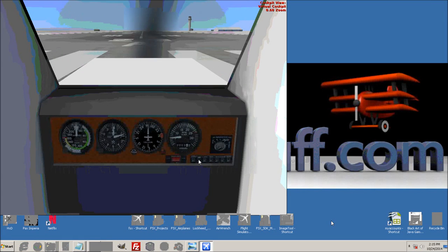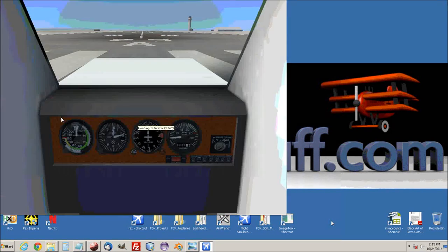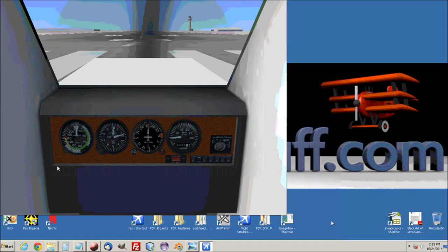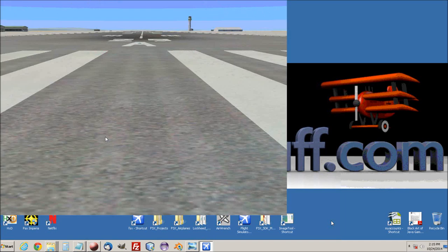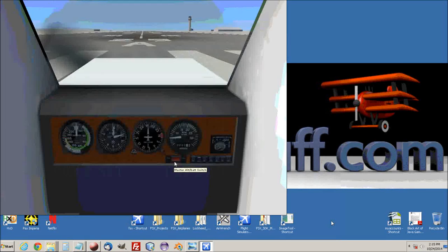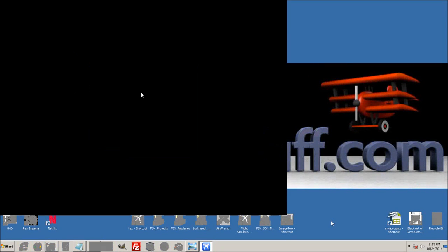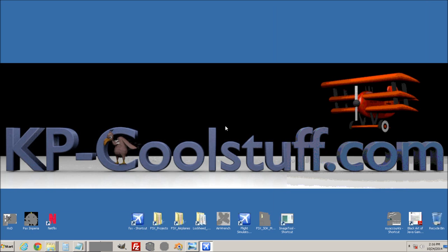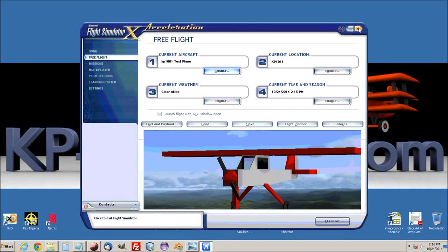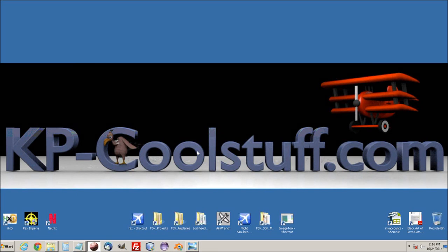Sometimes, you may have an invisible face or polygon in front of the face that you use for your instrument panel. If you have that problem, you have to go back into Blender and see if you can find what's in front of it. So I'm going to go ahead and exit out of this. I'm going to close this. So now you see how to set up your instruments for your instrument panel.